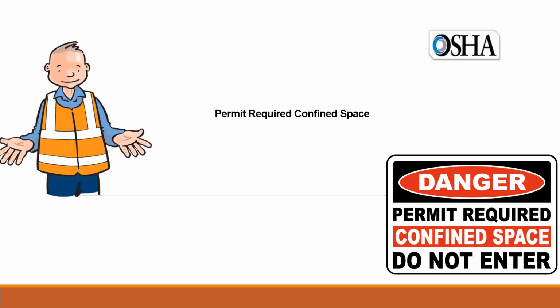The most common types of permits are the cold permit, which you use for any normal maintenance activity that does not require any hot job. Hot jobs are those jobs which involve some ignition, for example welding, cutting, grinding. These are all hot jobs. So the first type is the cold permit, the second type is the hot permit, which involves any cutting, grinding, welding activities. You make sure that the controls are applied while you are performing this activity.